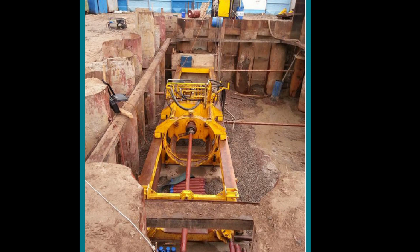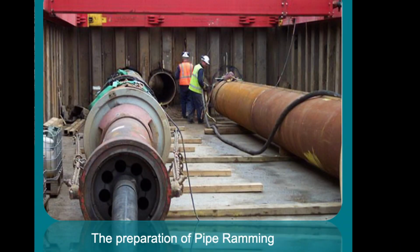The essence of the pipe ramming method lies in the fact that the pipe is pushed into the soil by its open end, and the soil which got into it during the moving of the pipe is removed manually or by hydromechanization tools. The pipe ramming method, you can refer to the figure, is utilized in case of laying pipes with large diameter from 800 to 1400 mm and on distances up to 80 meters.